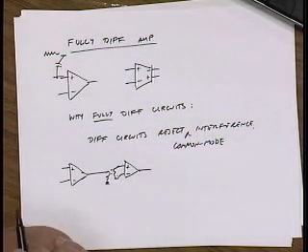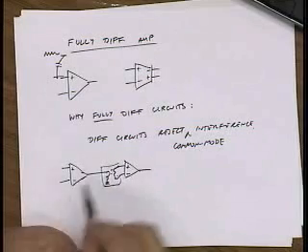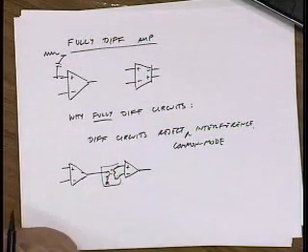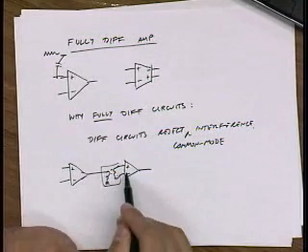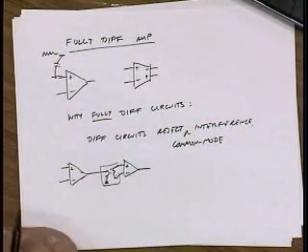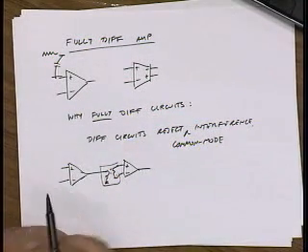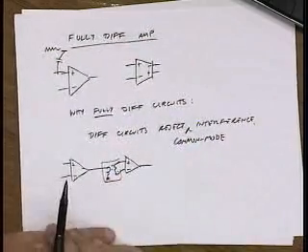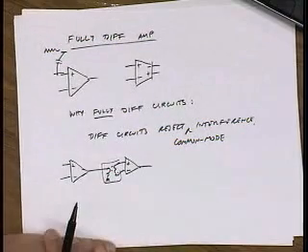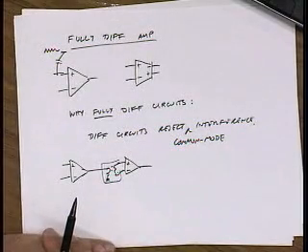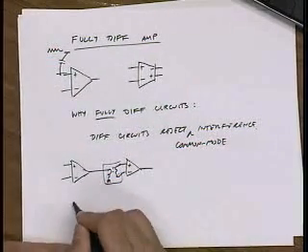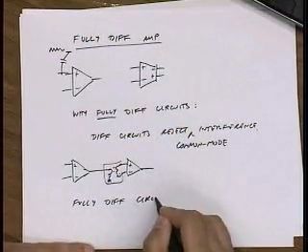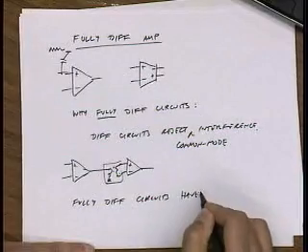a differential input. And I can't really use a balun, right? At low RF frequencies, I'd use a little balun on chip and generate a differential signal, and then that would again reject the common mode. So it's nice. These differential signals can drive each other. Is there another benefit? Yes. Yeah, swing. So fully differential circuits have twice the voltage swing.